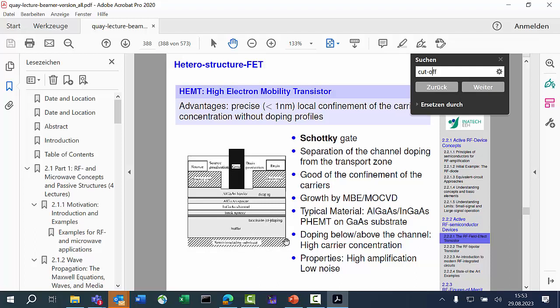And in opposite, that's also why people made memory small, to have as many memories as possible on a given area. So they made all the dimensions small, including also the gate length. They made the transistors very small in area. This is the width, but that is not the only thing. They also made the length small between the contacts. Which means that by reducing the size to represent the bit, they also made the switching very fast.